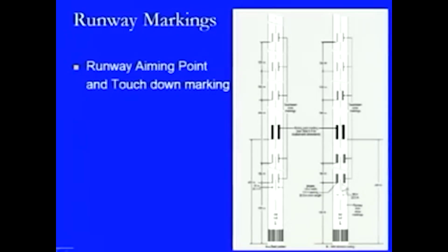Here in this case, as we have seen in the previous diagram, there are some more lines, like there are 3 lines and 3 lines likewise, and then there are 2 lines and so on, and then there is a single line, and finally, we have this much distance which is defined as the touchdown zone marking. So, this is with the direction coding, and this is with the basic type of pattern. Direction coding means the aircraft will be going in this direction for the landing.